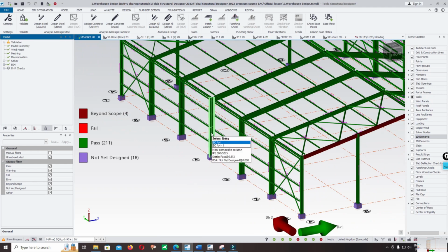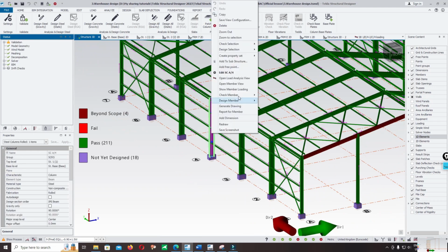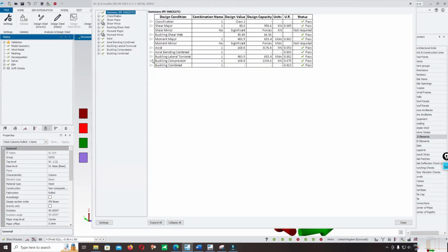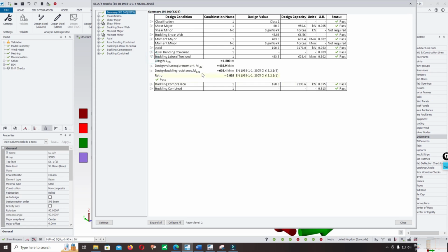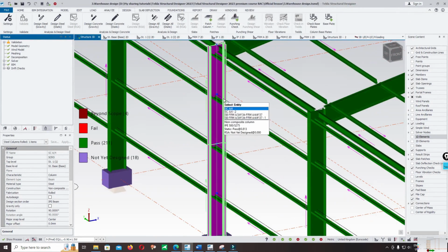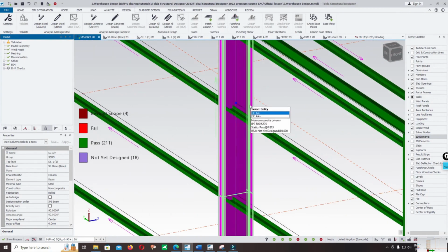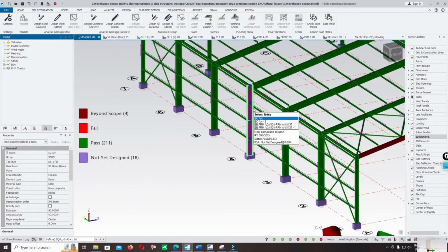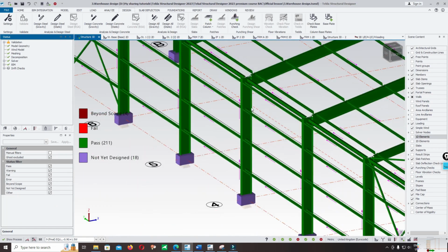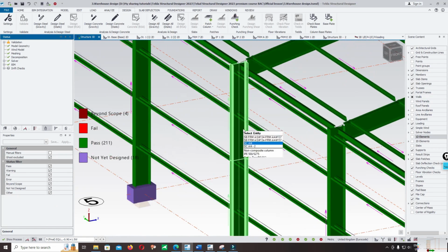Now check the middle column by right click and check static and check for the lateral torsional buckling. The LTB length is equal to 1.5 meters. So we have to add the lateral torsional restraint at the intersection of the purlin with the bottom plane of the column. I will show you later how we can add the restraint to the purlin and to the column.